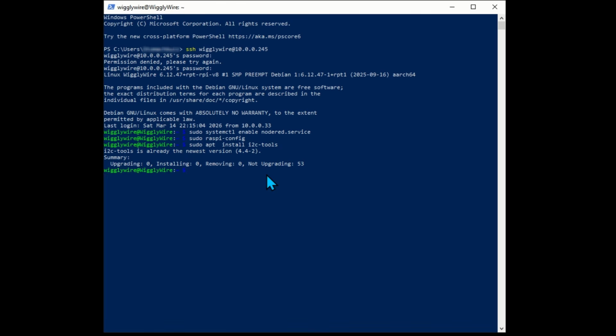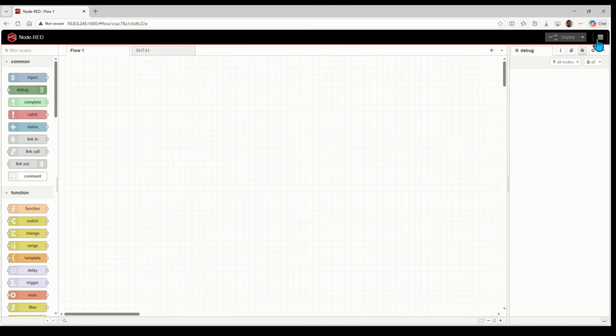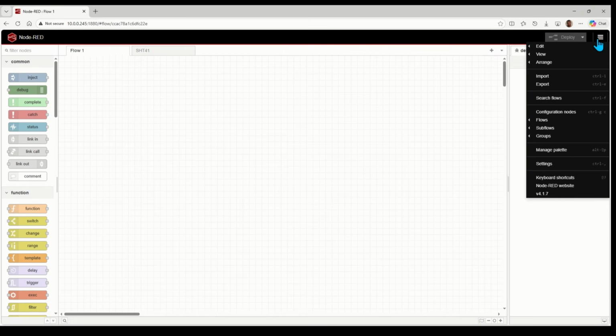Once the Node-RED service is running, the Raspberry Pi acts as a web server, and we can now access Node-RED via a web browser from a client computer. You can go to Node-RED by entering the Pi's IP address followed with a :1880 suffix. From here, install the dependent Node-RED palettes by clicking on the Hamburger menu tab in the upper right corner.